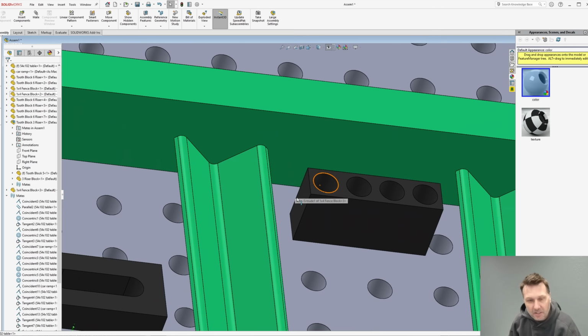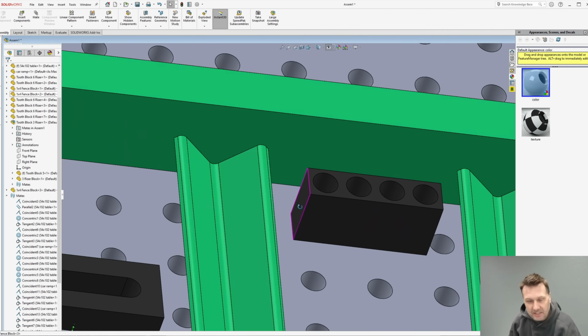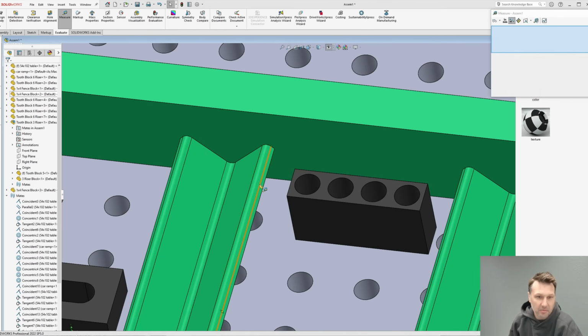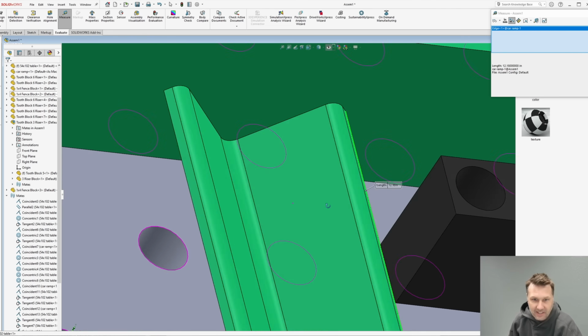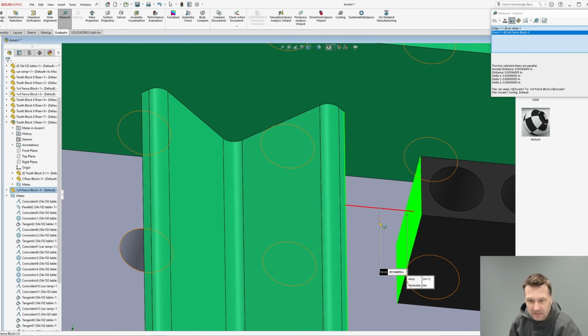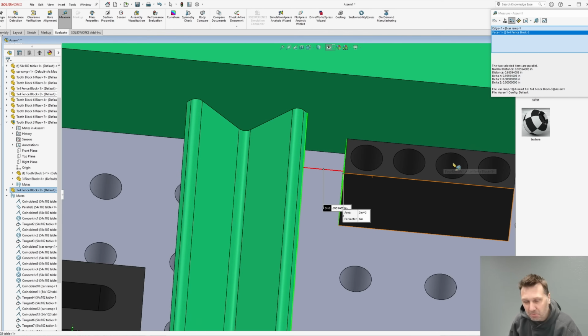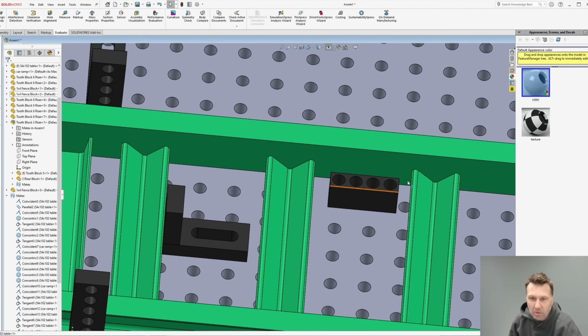And then what we're gonna do is we're gonna measure the distance between this block and this edge when we get to there. I'm gonna just kind of give us a little preview. That edge to this edge is almost 1 inch. I mean, we are 50 thousandths away. We could round it down to the nearest 16th or closest 16th. We'll take a look at that. But I think I'd round it to 1 inch and just call it that. If that was the case, I'd just probably flip this block around and be good. But we'll work on that here in a minute.